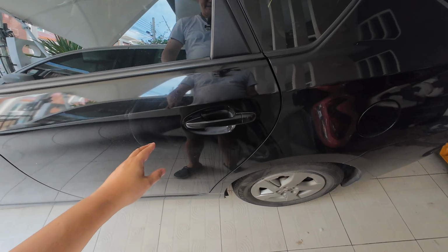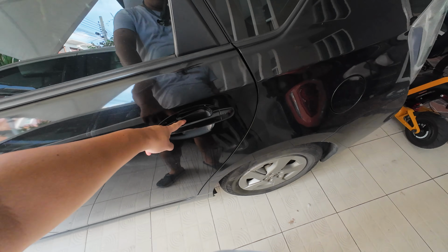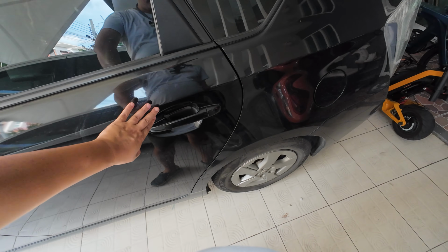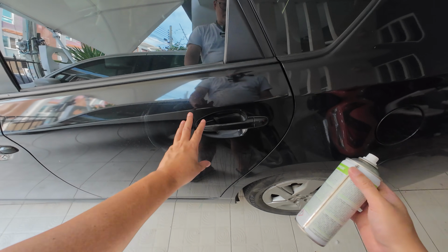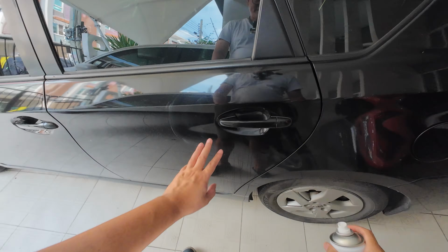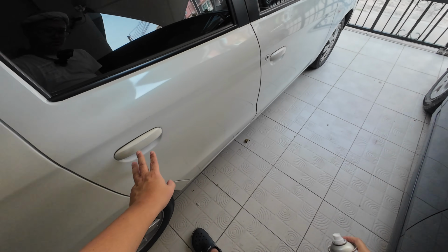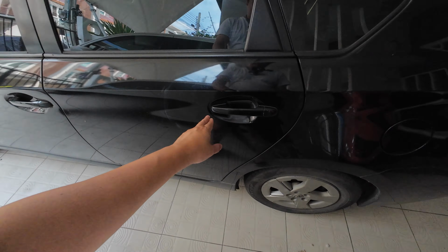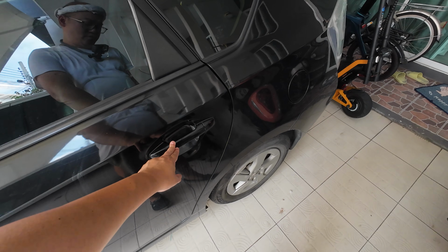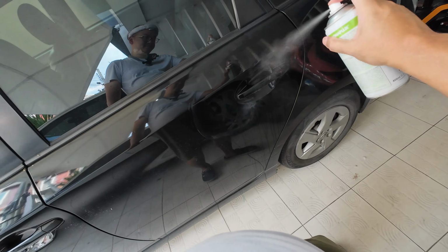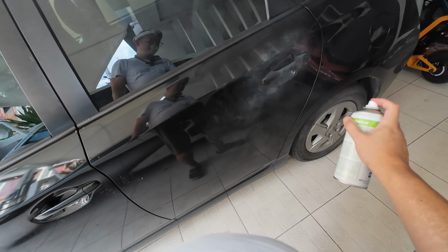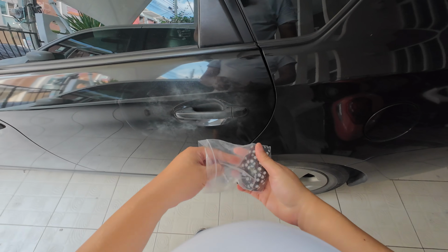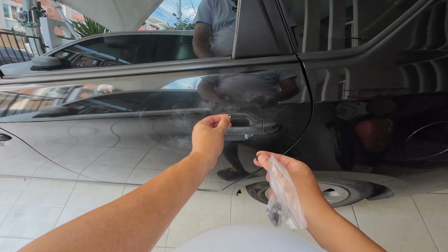Before we start the scan, the pocket of the door handle has a concave and it's in black color. So I recommend that you spray this even when I scan with a Raptor. If it's white color like this, you don't have to do anything. But if it's black and concave, you need to spray. So I use magnetic marker.